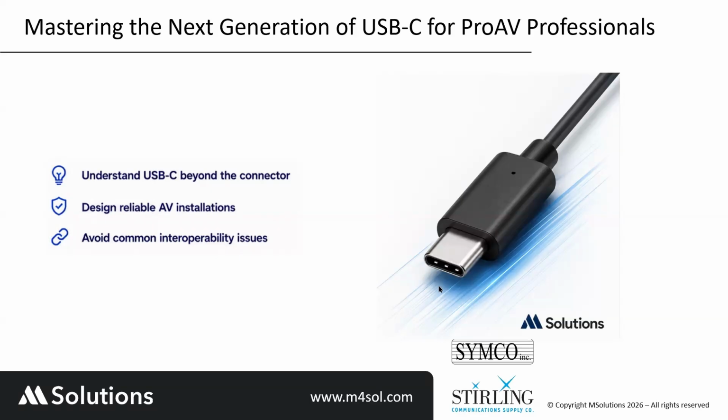Today, USB-C is no longer just another connector. It carries power, data, video, audio, Ethernet, and control signals all through a single cable. Yet many installations still run into problems because people assume that all USB-C ports are identical.